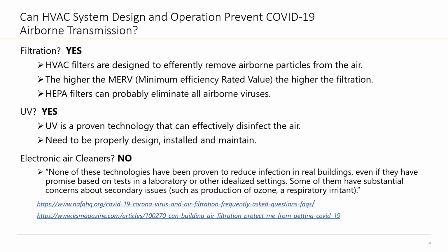Also, we, as the ASHRAE committee, never obtained a third-party certification of efficiency. And there's concern about byproducts. As I mentioned before, it's not only ozone, it goes beyond that: formaldehyde, ultrafine particles, etc. So you need to be very, very cautious in considering these devices and get third-party proof of efficacy.